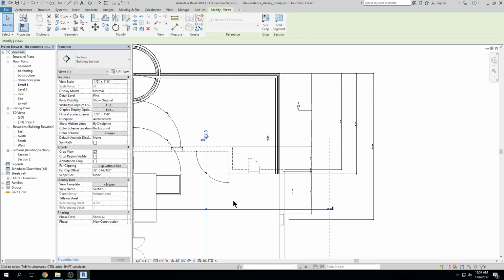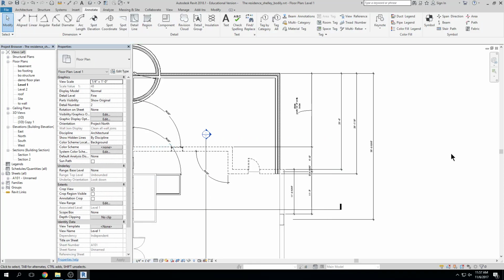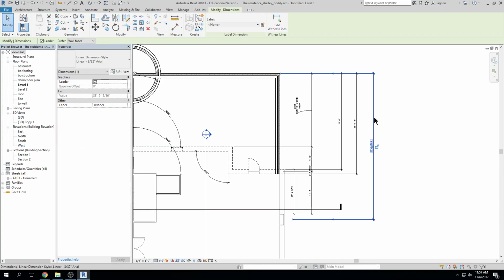Everything updates to the scale that is currently shown here, which even though it's not a perfect system, it's much better than it was, right? I really only need to have one dimension style and everything works, okay? And in AutoCAD, before annotative scaling, annotative dimensions, we had multiple dimension styles that we used, okay?